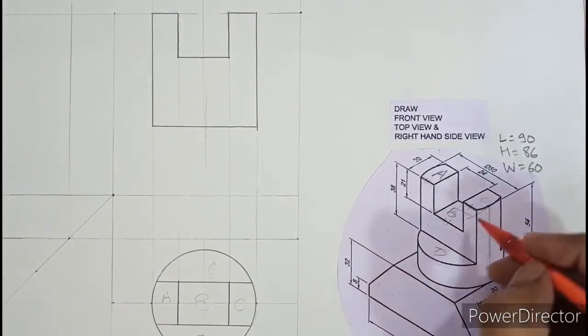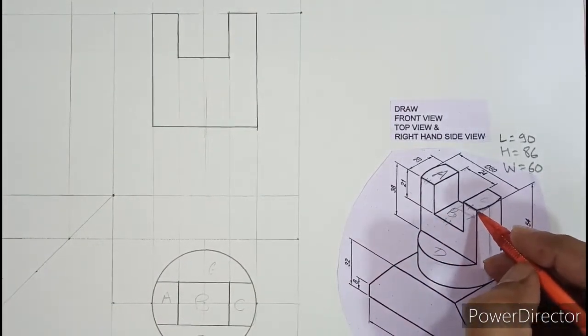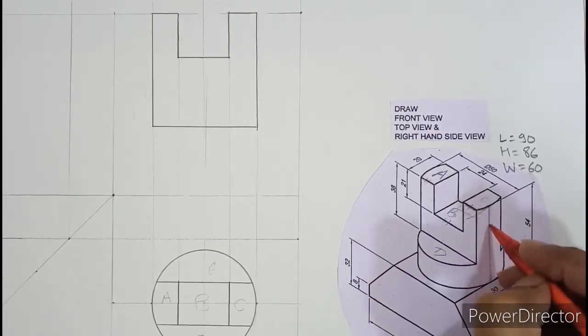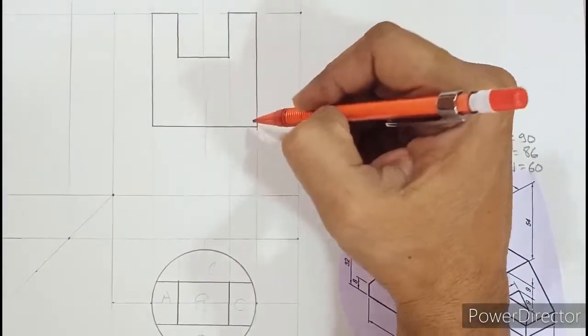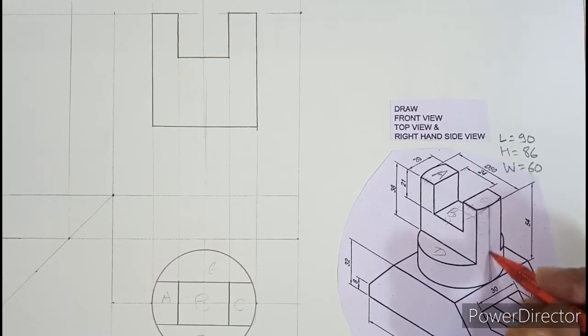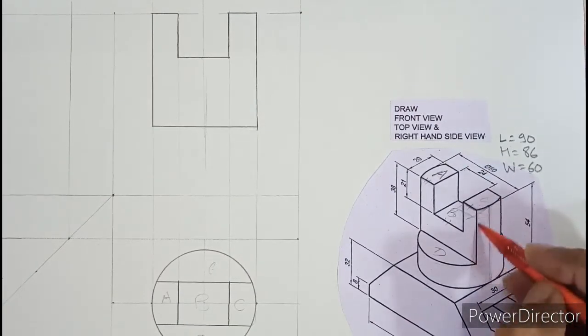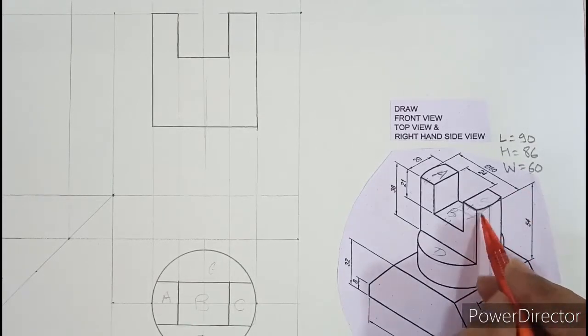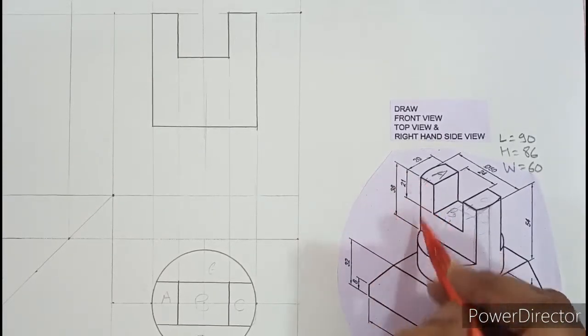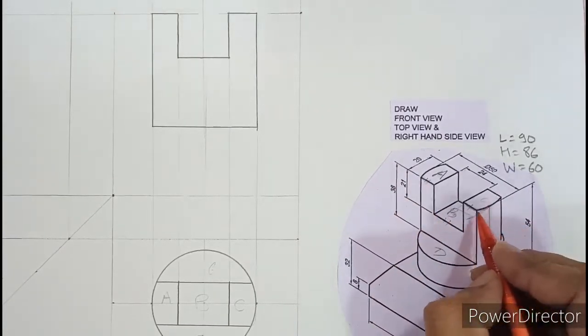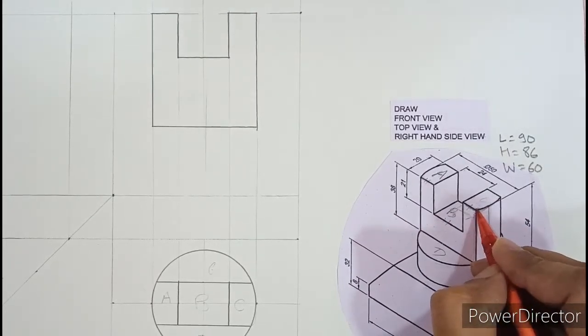Now the next important part I wanted to discuss is, apart from this cutout, you can also see this vertical edge. Because the line you've drawn, this line is actually the boundary of the cylinder. So this line resembles the boundary of the cylinder, but this vertical edge is a separate edge. Both these lines are separated by a circular surface. So this edge we need to draw, and the depth is 38 millimeter. So the height of this line is how much? 38. But how will you locate this point or this edge?